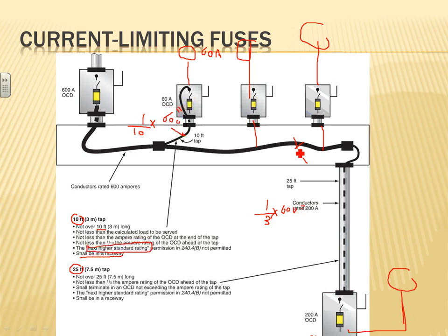Is that what you meant by the feeder, Dave? When you take a feeder and you feed multiple of them from a panel? It doesn't have to be this way. It could be another panel too. Well, it doesn't even have to be tapped. You can have a separate overcurrent protection device on that feeder for each one. Yep, the same size. You have to coordinate the overcurrent protection devices. Any comments, guys, about the taps?